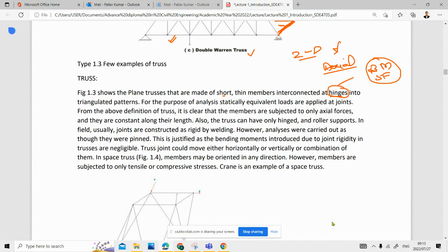You need to speak only about axial forces. People may confuse you while you are interviewing, or while they are asking that, they just check your knowledge, right? So whenever they say the word truss, forget about BM and SF. Just think about axial compression and tension in that member. I have seen people drawing bending moment and shear force diagrams for trusses. Please don't make those mistakes.